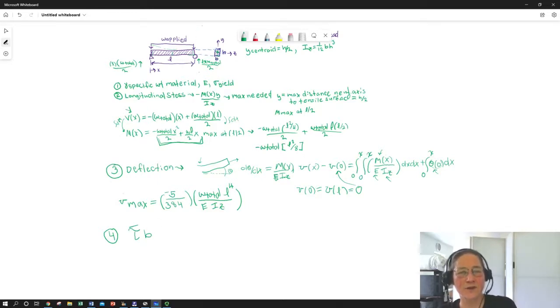So the average shear stress across this face times the width of the face b is equal to, referring to my notes, shear force at whatever given x position we're looking at, divided by, again, our moment of inertia. Notice this comes up in every limiting expression. Now we know why things are designed for big moments of inertia.